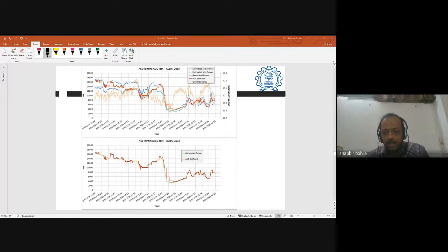Sir, you have already explained that, but I just want to ask a question. Maybe I don't know whether it is at the correct place or not. You have shown that in the solar photovoltaic as well as the wind system, the system may not be operating at the MPPT point, just to keep some safe margin. So it means that all the time we have to operate the system at other than the MPP point, or when it is anticipated that there is going to be some change in the system, we predict that and then shift the operating point from the MPP to some other points.